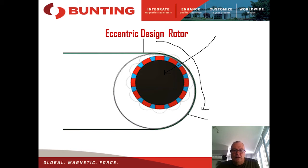It means that this area here down the bottom is an area of low magnetic field, which means that we don't have so much of an issue of magnetic particles being attached here, wearing the belt out. So we have a better release zone for non-conductors in this area because we have a lower magnetic field. So it does have some process advantages.